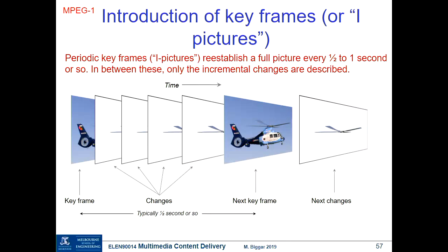If we had a long sequence of 10 minutes of video, always each frame coded differentially from the one before, what would that mean? Quantization error may get higher and higher. What gets higher? When prediction is not correct... Oh, well, one problem could be if there was an error. Is that what you're saying? So an error would propagate forever.